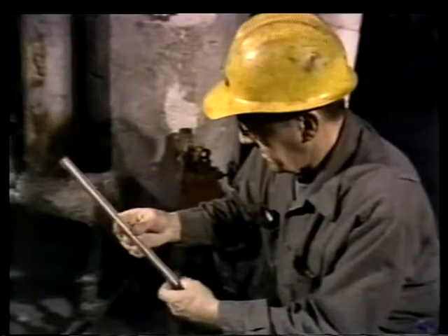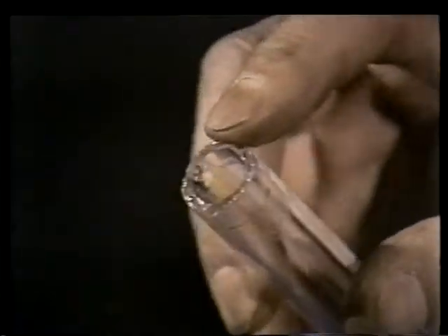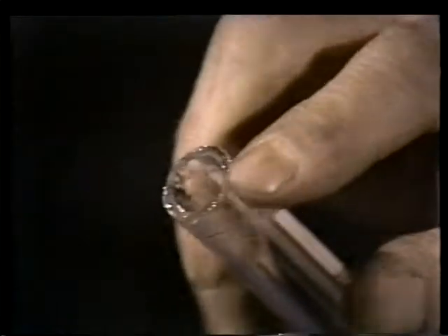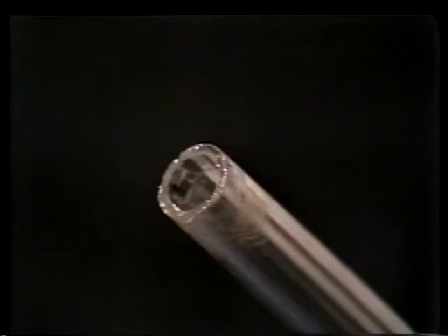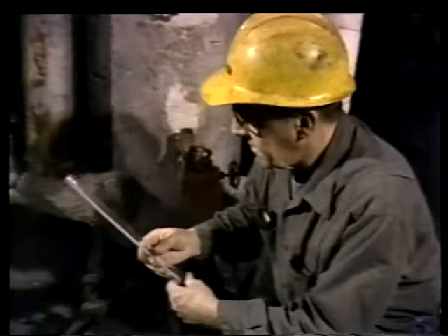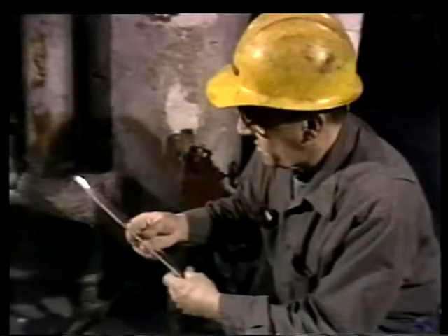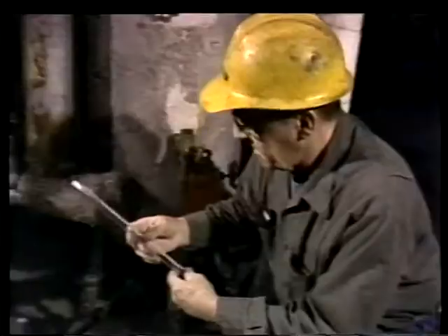Inspect the glass for imperfections. Pay particular attention to the ends of the tube. If these aren't smooth and round, the gauge will not seal properly when it is reassembled. A glass tube that is chipped, cracked, badly scratched, eroded, or stained should not be reinstalled in the gauge.